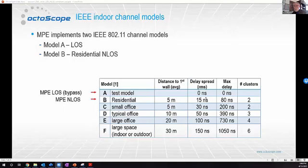But we also implement Model B, which is the residential non-line of sight. It has 2 clusters, has a delay profile, and introduces frequency nulls and so on in the frequency response of the channel. So these are pretty good models, quite representative of a typical environment for Wi-Fi. I'm going to pause if there are any questions at this point.